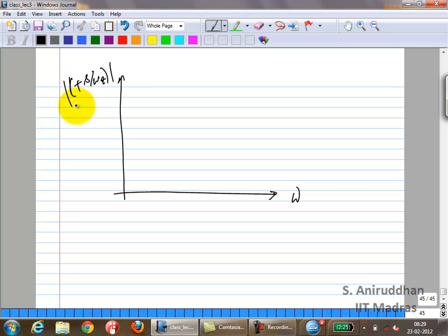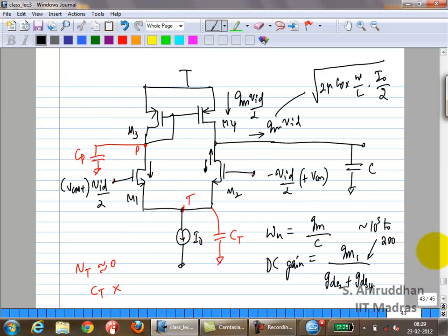So if I just take these two portions over, I have one pole and one zero apart from the integrator. If I just plot the gain of this, what should it look like? Actually, if you just look at the circuit, what is the gain at very high frequencies? What is that GM at very high frequencies? That is another way to find out what the zero location and the pole location should be. What is the effective transconductance at very high frequencies?